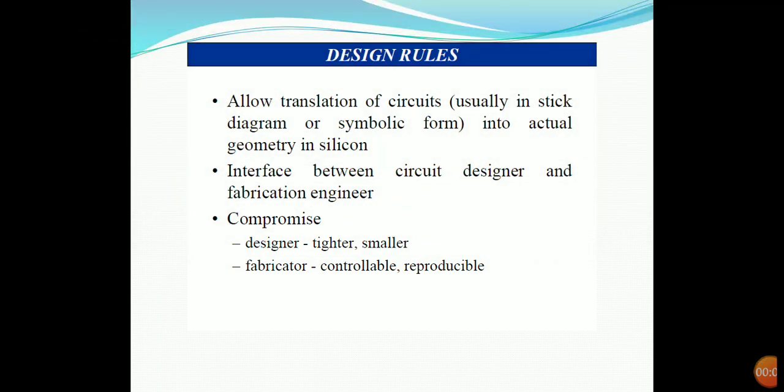The design rules are a set of rules which allow the translation of a circuit into actual geometry in silicon. The circuit design will be converted into geometrical form in the silicon. Usually, this circuit will be in stick diagram or symbolic form, and the rules are the interface between the circuit or system designer and the fabrication engineer.